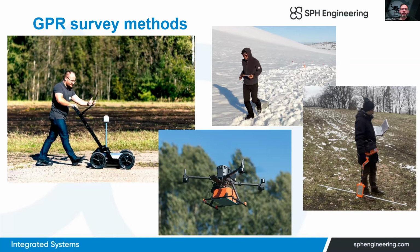But if you consider drone-mounted GPR applications, why can GPR on a drone be optimal? First of all, if you need to survey large areas without obstacles and vegetation, or with very low vegetation. Or when it is hard or not safe to walk in the survey area, for example, over a glacier.